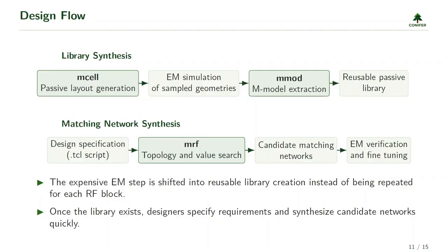We can see that the expensive step of electromagnetic simulation is shifted into reusable library creation instead of being repeated in multiple iterations for each RF block. This is a major speed up. Once the library exists, designers can specify requirements and synthesize candidate networks quickly.